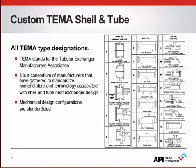The design reduces the ability to have a full tube count, and an even number of passes is typically required as well. The U-tube is also very common. It allows for thermal expansion and a removable bundle. It is also very versatile, but limited to no temperature cross types of applications, which again we will discuss in a little bit. Unless there's an F shell that is used, then the U-tube can be employed with temperature cross.